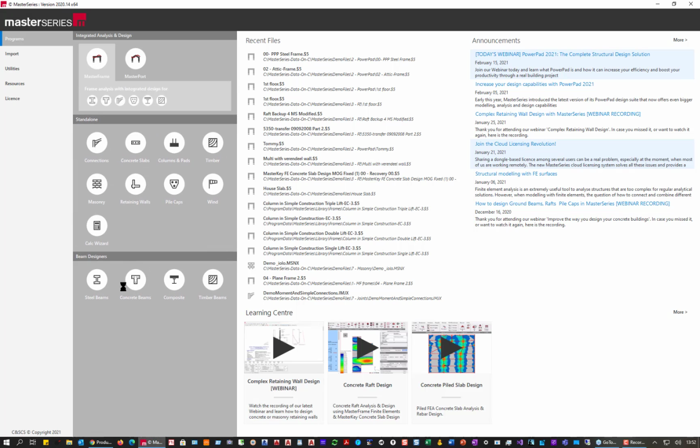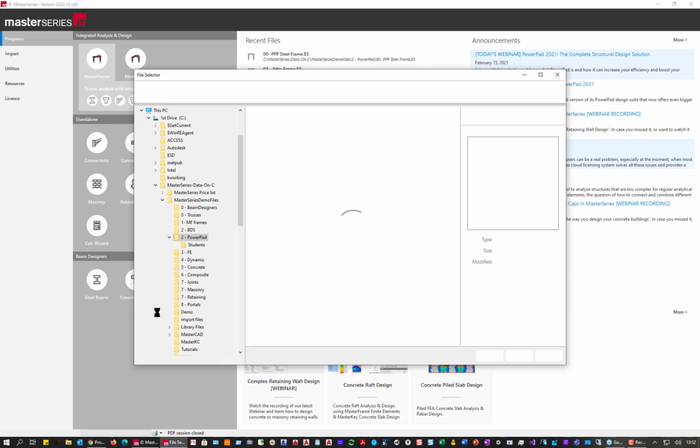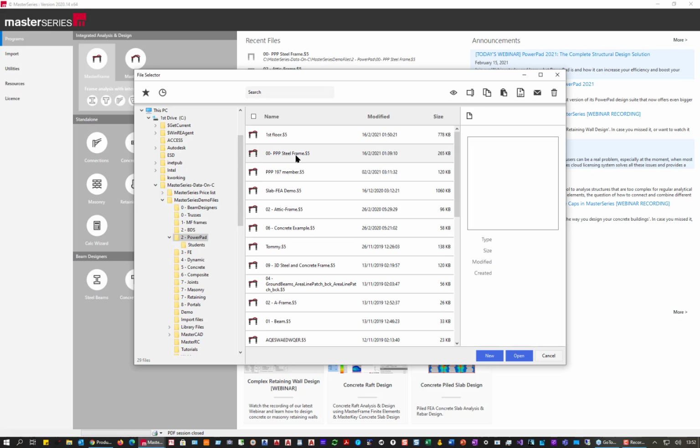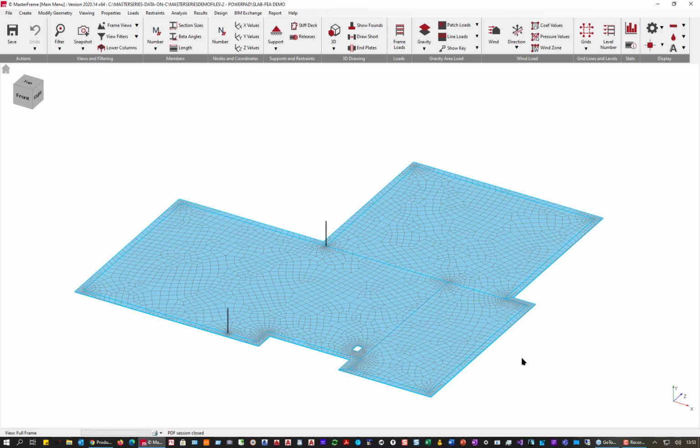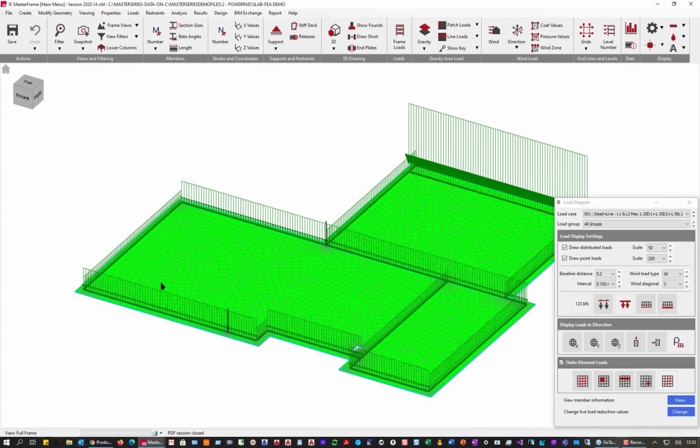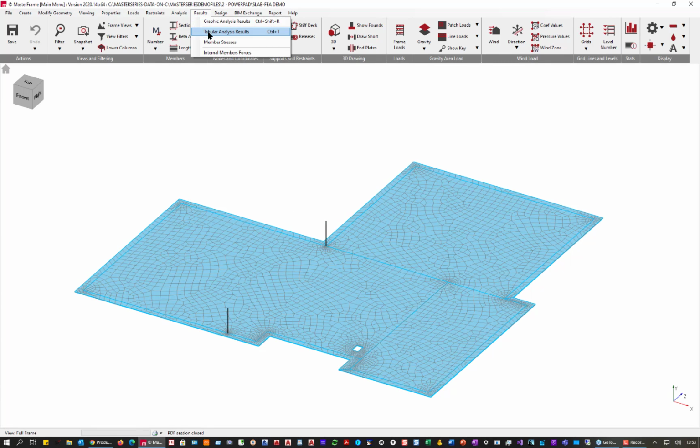Okay, let's go in and look at my other little piece of FEA, just to give you an idea of the more realistic design. And yeah, that's the one. It's a little house extension with different loading on the two floors. Or I should say this is two-story area and this is one story, so the loading coming around it is higher, spanning that direction than that, and then obviously there's a big wall at the back. So it's interesting, plus a couple of point loads. So that was very easily done